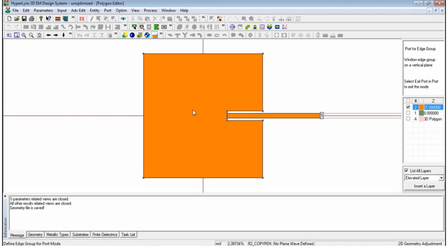The next thing is what we need to define. We need to mesh our structure. The meshing is nothing but this is the whole structure. We need to mesh. Mesh means it will divide this whole structure in smaller cells, and the results would be calculated on individual cells, and the final result would be the integration of a particular cell's results. So the finer you mesh your structure, the more accurate your results would be. So what we'll do, we'll mesh this structure.